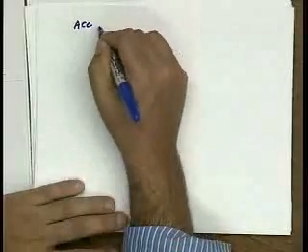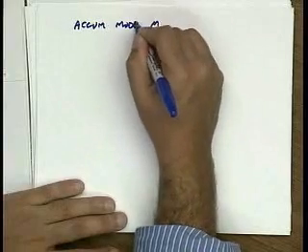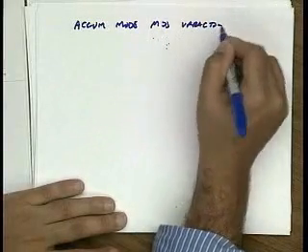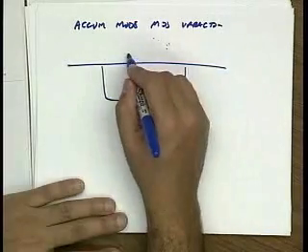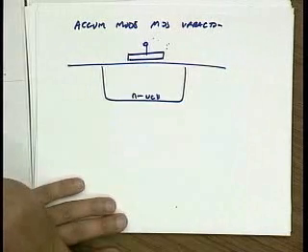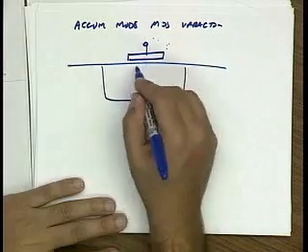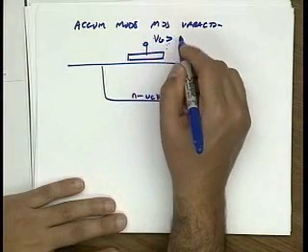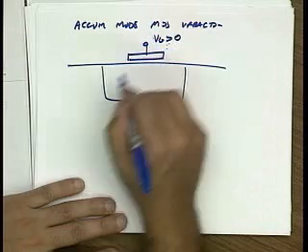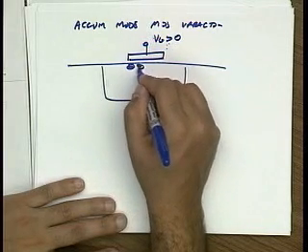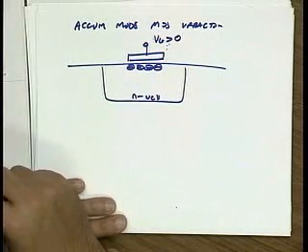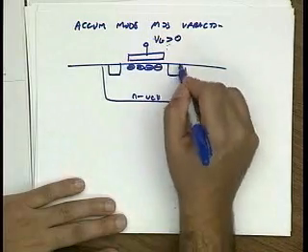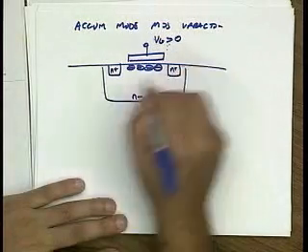So what would the accumulation mode N-type look like? So this would be an accumulation mode MOS varactor. Basically, you might think just build a PMOS device. So we have an N-well, and I'm going to put a gate voltage here. And I want electrons to come to the surface, so I put a positive gate voltage, and that would accumulate electrons basically at the surface. And that's great. Electrons have good mobility. And the other terminal I would form by making a bulk contact. So I would put an N+ region here.